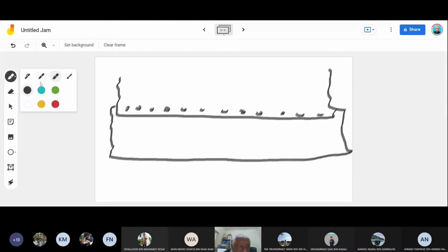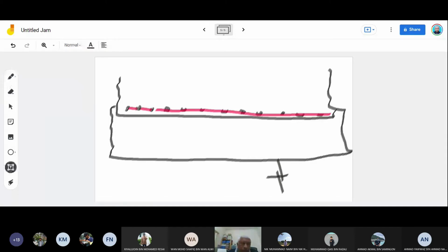Because of the fatigue problem, the crack grows across. That's why this part is broken off. If we look from the side, how it looks from the side: skin, and we have rivets, and all these are joints.